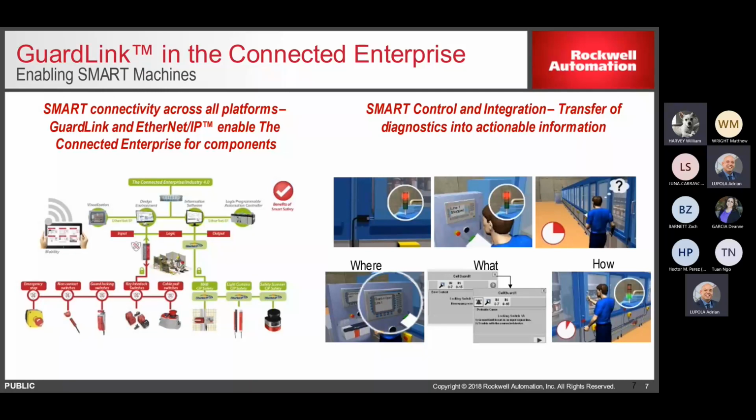I get some diagnostics over the same 4 wires. So it simplifies my wiring for interlocks and e-stops and interlock switches and my cable pull switches. But again, simplifies the wiring. I get diagnostics. I don't worry about fault masking and some other good things with that.